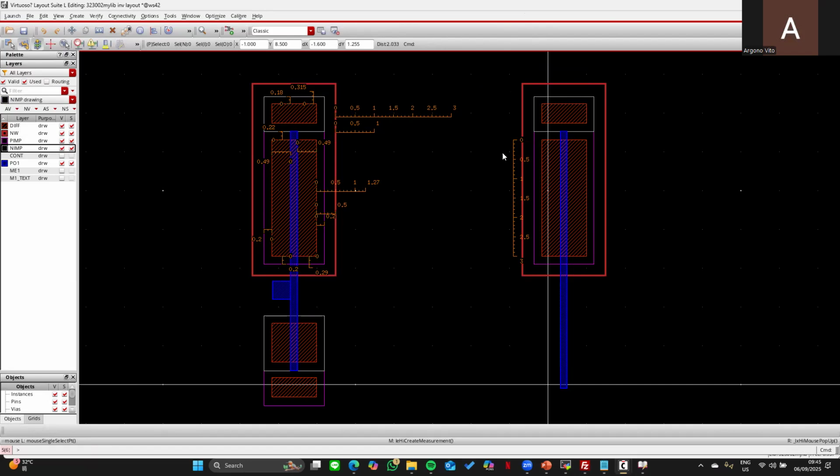So done for PMOS. Then you need to create a contact or interconnect. So the best scenario you can draw, you need to fill as many vias as possible inside the diffusion region, and the via size is 0.23 times 0.23, and then the distance needs to be checked.